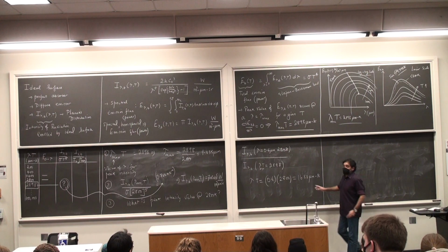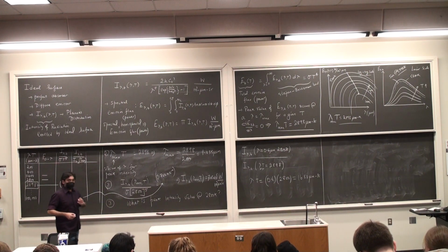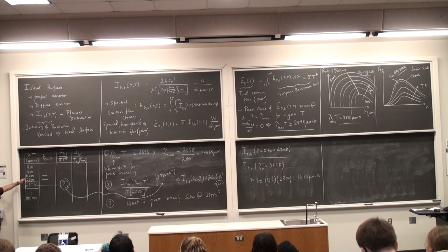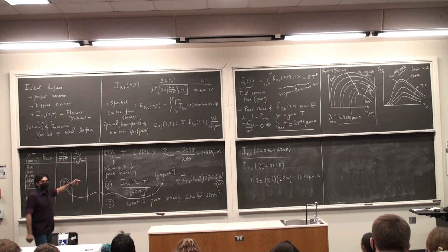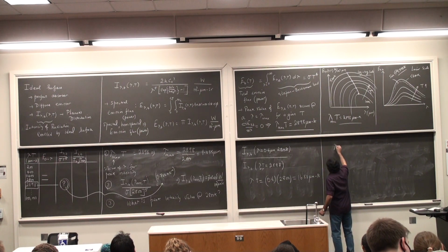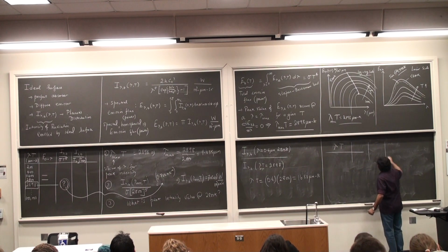It would be nice if 1680 were present on the tables. It most probably will not be, but I will have a value of lambda T equal to 1600. I will have a value of lambda T equal to 1800. 1680 is in between these two, so I have to interpolate. Okay? So very briefly, I look at the lambda T entry, other columns.